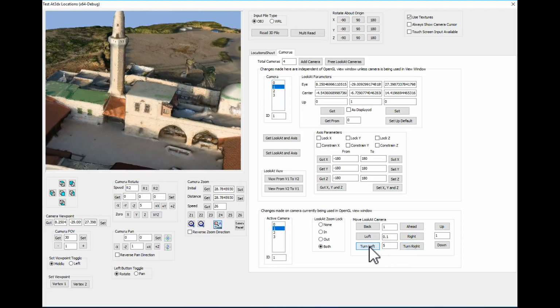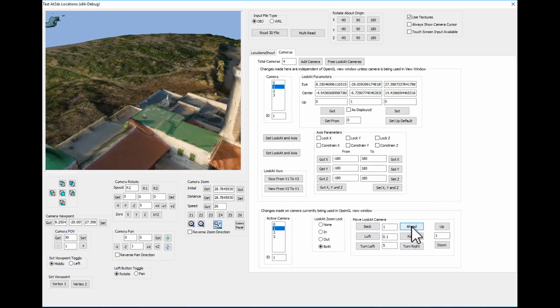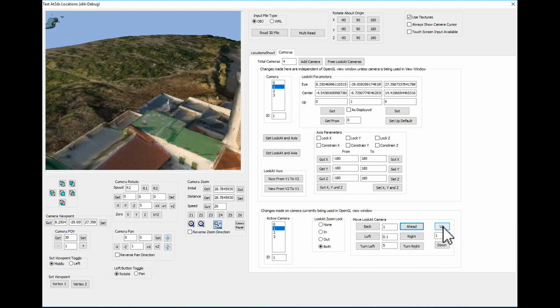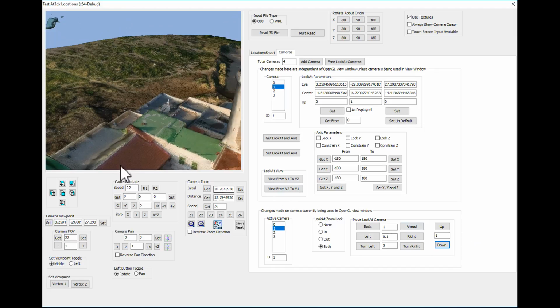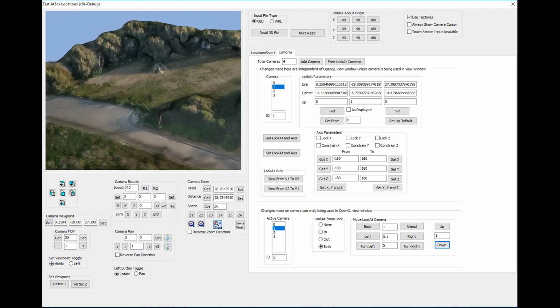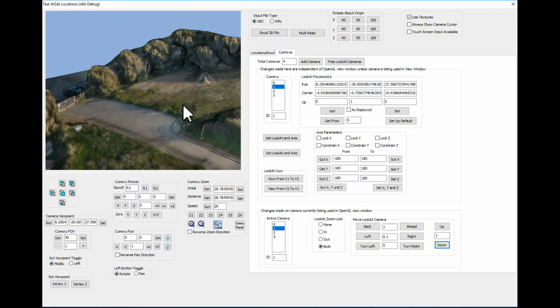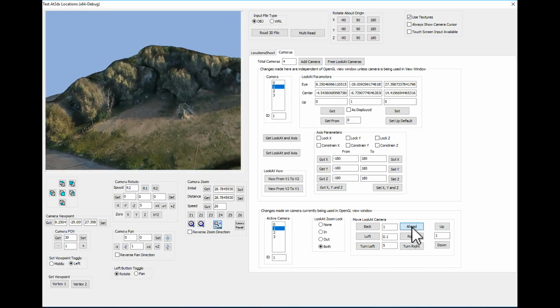and turn to the left, and wherever I finish turning, if I go ahead, I'm going to be going in a new direction. I can go up with the camera and I can go down with the camera. Once I'm looking around in the view, I can be rotating around, and then I can say, oh well, I want to go off in this direction. Well, I can set a new viewpoint for the camera by either clicking on the middle mouse button or setting this button to left and double clicking. And now if I move ahead, you can see I'm going in this direction.